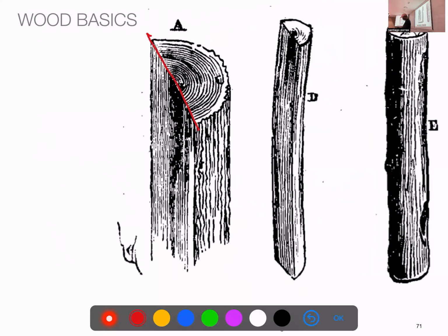And he explains the half cut of a timber. If you let it dry, it will bend this way. Why? Because it is the fibers of the rings which shrink, and you have more fibers on that side than on the inside, right? So it will pull more. Also, the longitudinal shrinkage is not as extreme as the transversal. In a very long element, that will happen. And since in roofs and in construction we need many long elements, it's interesting to be aware of that.